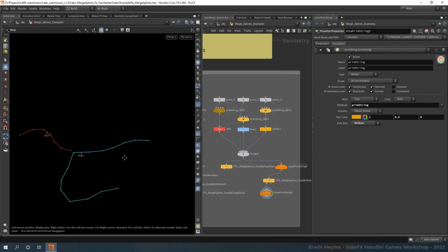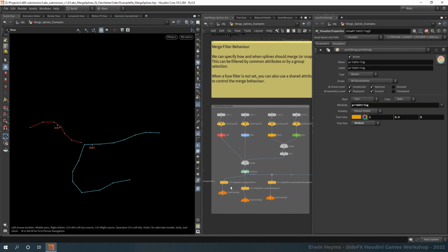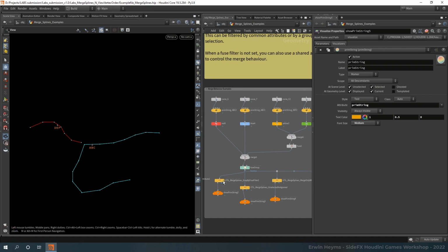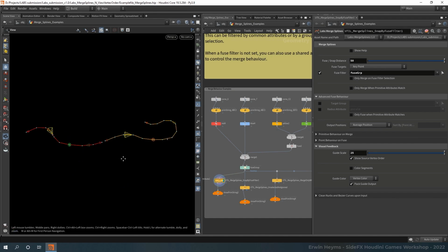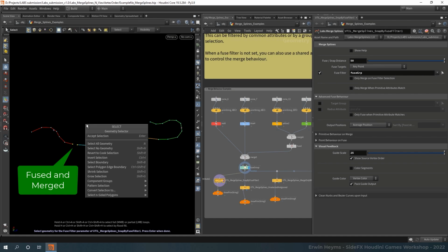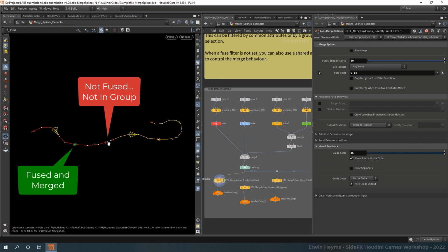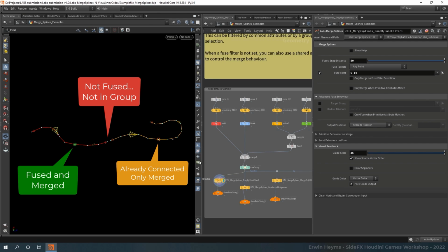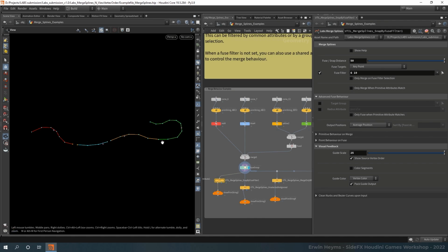And then finally, let's have a look at how we can use that filter to limit our operations and only affect curves we actually want to adjust. And when I go to the final example for the roads, this is very useful. So over here, I have several curves and they're all being combined together. At least as long as they are within this filter here, they can snap. These two cannot, so they are kept apart. But because these were already connected, they are also merged into one curve. You can see they used to be two curves, now they're one.